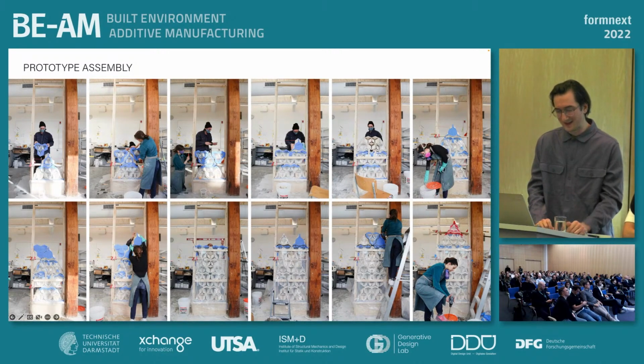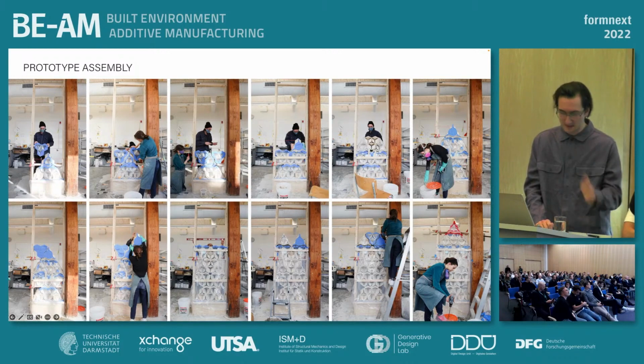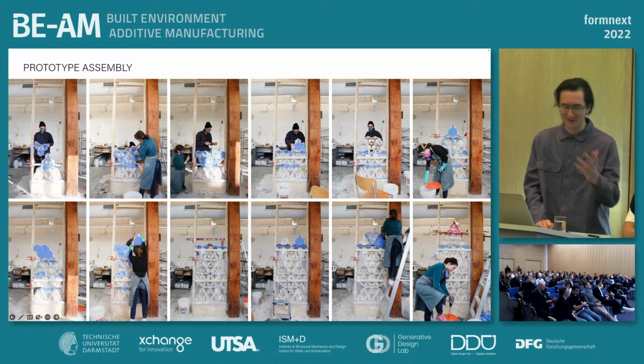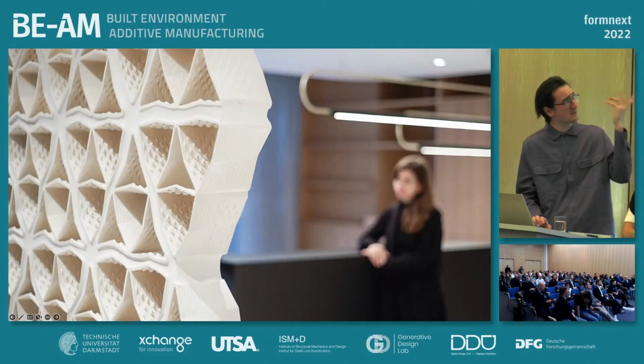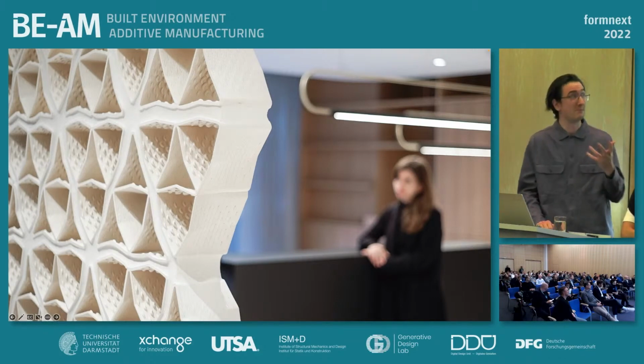So in order to respond to the dynamic material qualities of clay and formulating suitable mixtures for 3D printing at such an extensive scale, there was extensive material testing, multiple assemblies and mock-ups required to prove that we could do this to all parties involved, the architect, the client. There was lots of convincing that we could do this. And that was the final proof of concept. So here's a shot of the edge condition that fully illustrates that mortar bonded freestanding wall. And we worked very closely with masons throughout this project to ensure that assembly was as simple as possible.